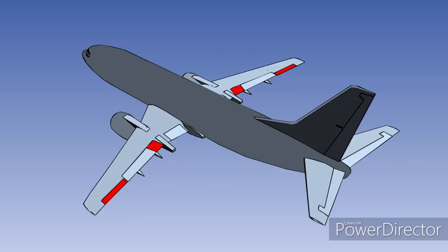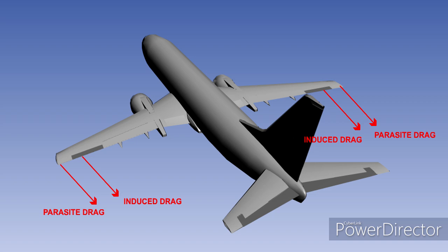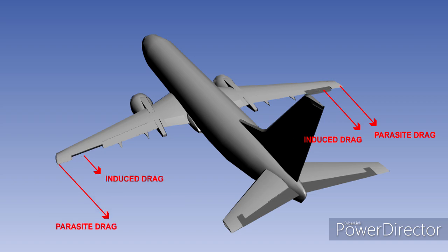Inboard ailerons are used to reduce wing twisting for high-speed flight. The outboard ailerons are normally disabled when the trailing edge flaps are fully retracted. There are a number of methods used to counteract adverse yaw, the most popular being differential ailerons. With this system, the upgoing aileron moves through a greater angle than the downgoing one, to equalize the drag on the wing.